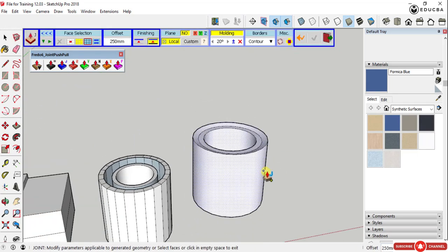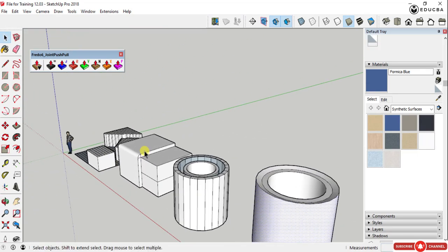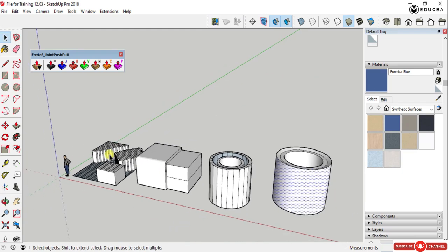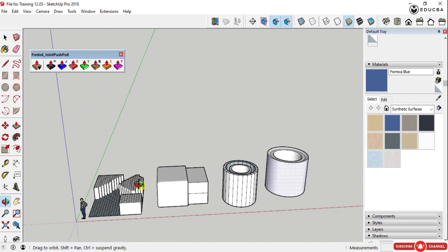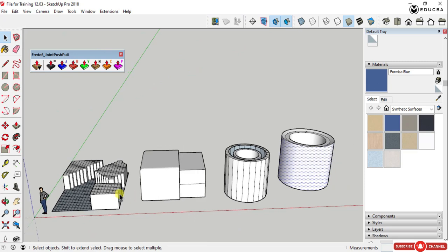So thickening surface is even easier with a joint push pull. Similarly, we have vector push and pull, we have normal push and pull, as well as extruding and follow push and pull. You can use these as you go on discovering what kind of commands they take up and what kind of results are out.